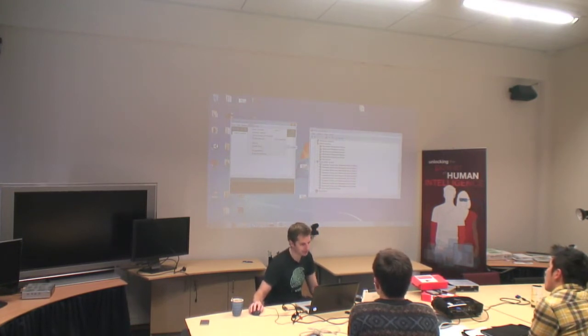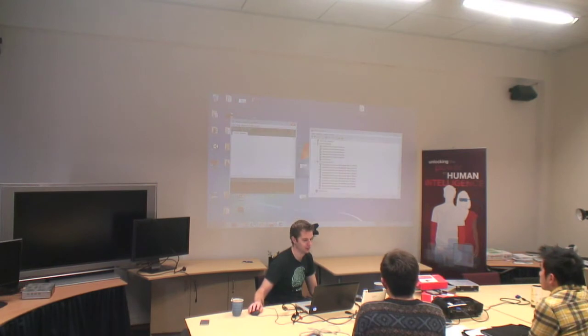But you want to go down to Serial Port and make sure you're on the right serial port. So you see USB Serial Port COM8. I want to make sure COM8 is selected. And then for Board, all the ones which come in these SparkFun kits are the Arduino Uno. So you just click on that and we're ready to go.